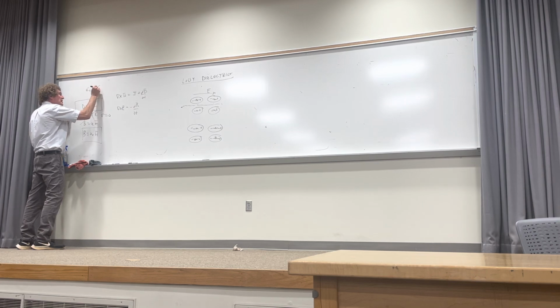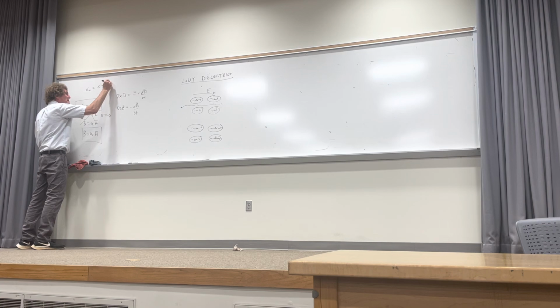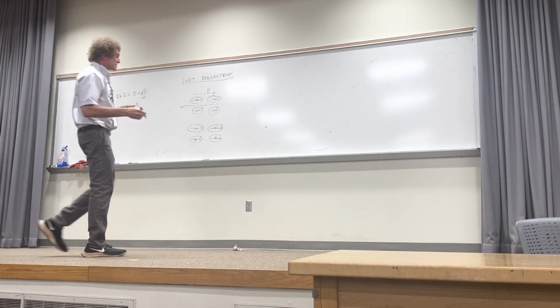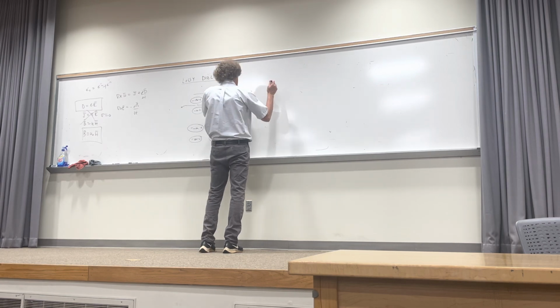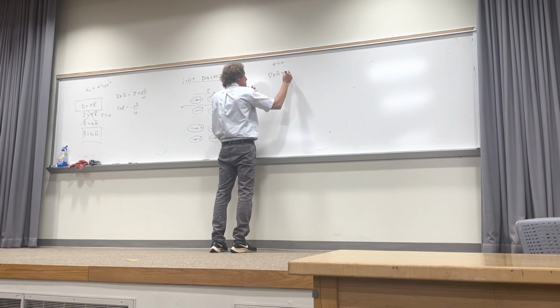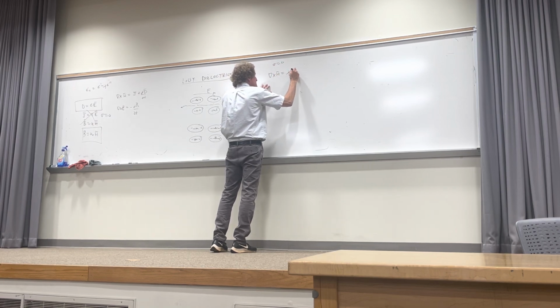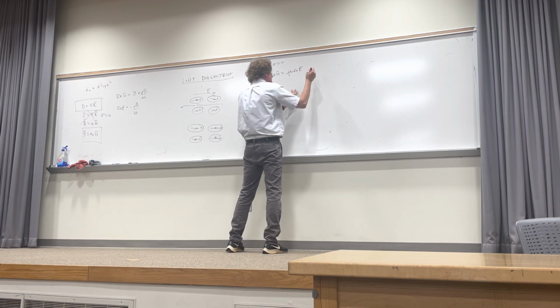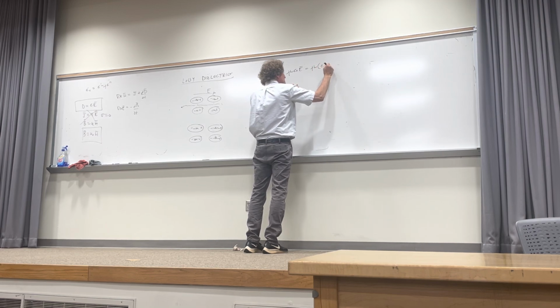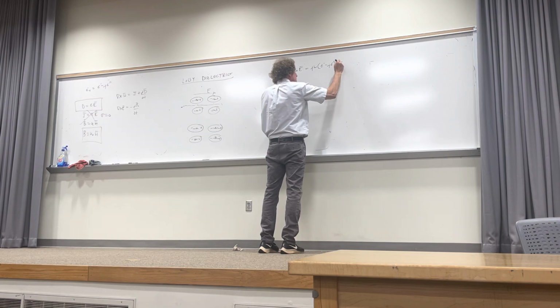And that's equal to some epsilon prime minus j epsilon double prime. This is going to bother you a little bit. You're going to say, now going to the frequency domain, I didn't say that explicitly yet. But the minus j epsilon double prime accounts for the lossiness. And you'll see this now the way I do it. So I'm going to go to the frequency domain. My first one is going to be curl of H. We're assuming sigma 0 will be equal to j omega epsilon complex E. And that's equal to j omega times epsilon prime minus j epsilon double prime, times E.